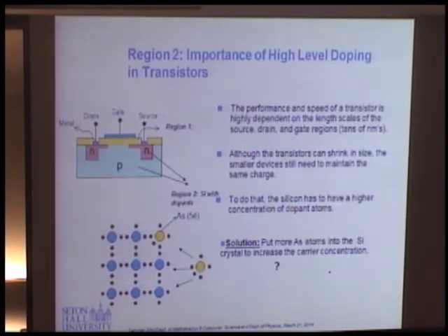Okay, we work with arsenic dopants. Remember, for the arsenic region, we want more arsenic in a small material. That was the thing. It's kind of a solubility, all right? So this is the silicon. It's a very simple two-dimensional picture of the silicon. You put the arsenic atoms, which is the yellow ones, and which has an extra electron. You see this extra electron? That's a free electron. It's going all over the place. That's the goal. You want more arsenic, you get more carriers. That's what you want in that region. Now what happens if you put too much?